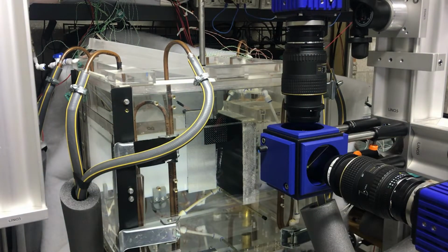And finally, we can use this to calibrate the cameras. First of all, we want to make sure the cameras are in focus, and then we want to perform an optical calibration, which means we relate the distance in pixels to a real life distance, in terms of millimeters or something like that.